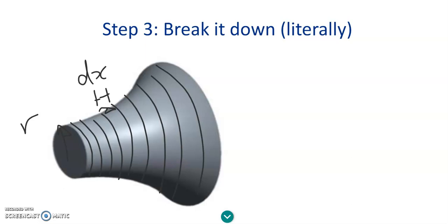And then that's going to allow us to find the area. The cross-sectional area of these discs, A, is pi times r of x squared. Remember that the radius changes with x. And then we can find the resistance of one of these small discs.